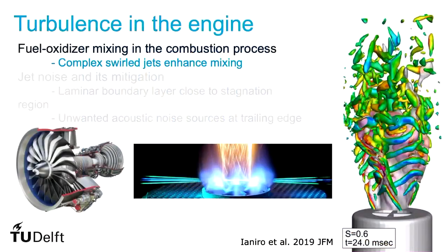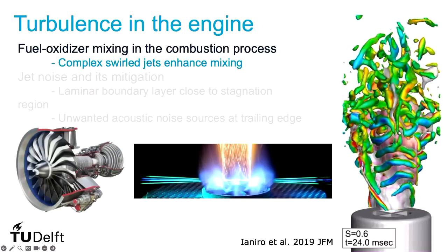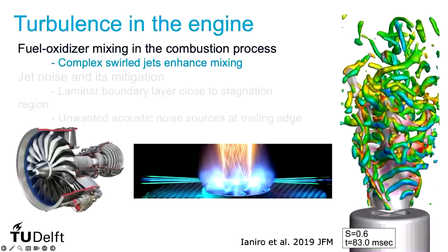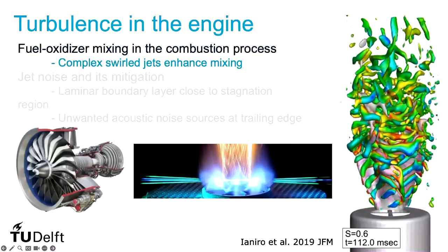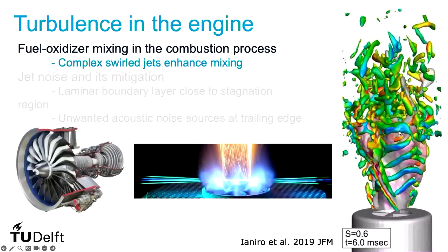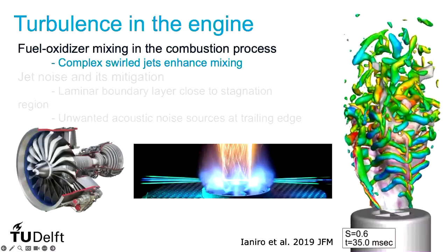The second part, again related to aviation, is the use of PIV to study the complex fluid dynamic situation in swirled combustors. Of course, in this case, one cannot simulate the entire physics, including the combustion, but in a water facility with a swirler with vanes, one could capture, I will explain, this is done with time-resolved tomographic PIV.